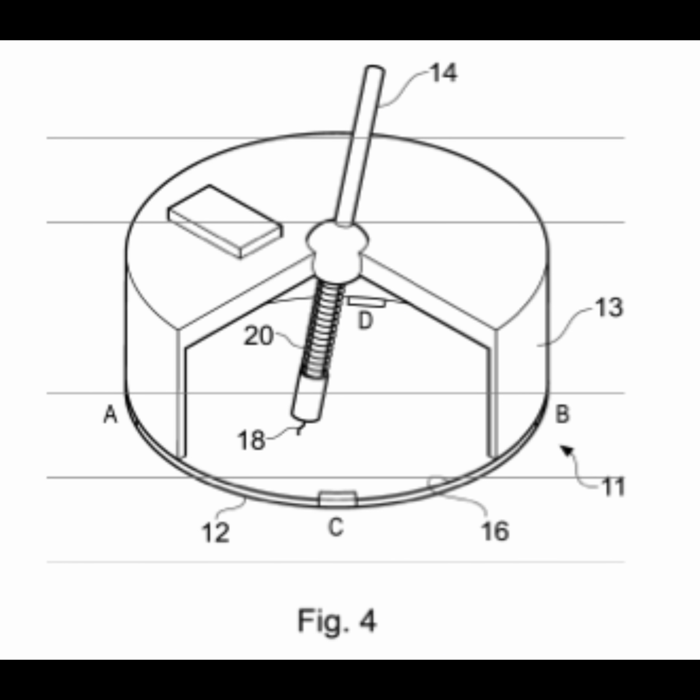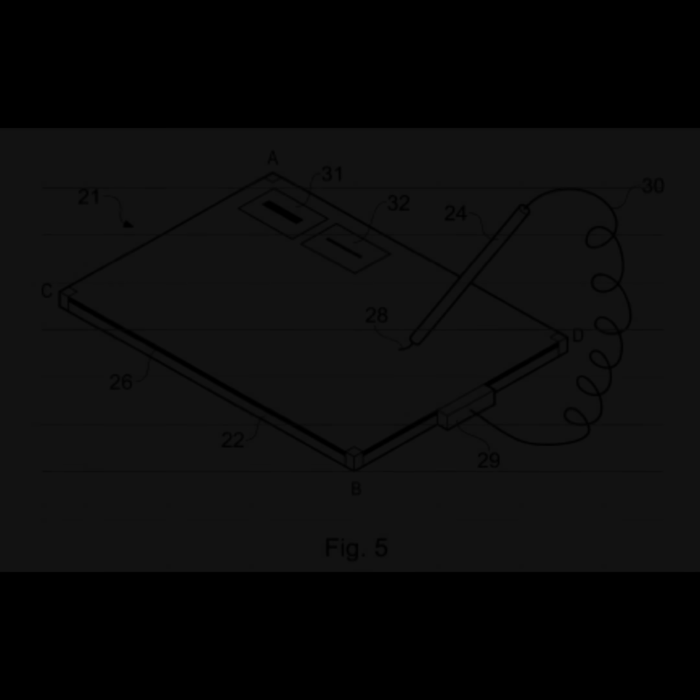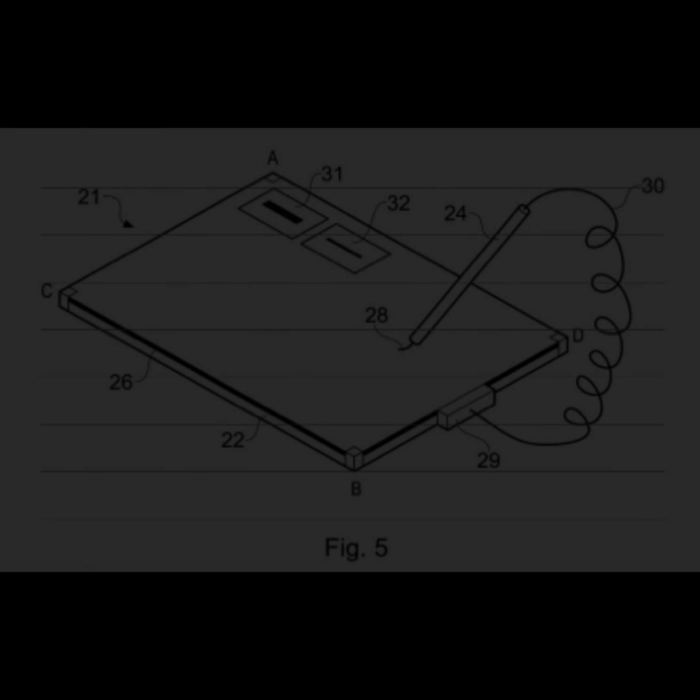So that the conductive element 28 makes contact with the resistive layer 26 and picks voltages off the resistive layer. As described in conjunction with the first embodiment, the control unit 29 converts voltages picked off by the conductive element 28 into output signals for a computer. These output signals represent coordinates of the points of contact of the conductive element 28 with the resistive layer 26 and may be used by the computer to create drawings.